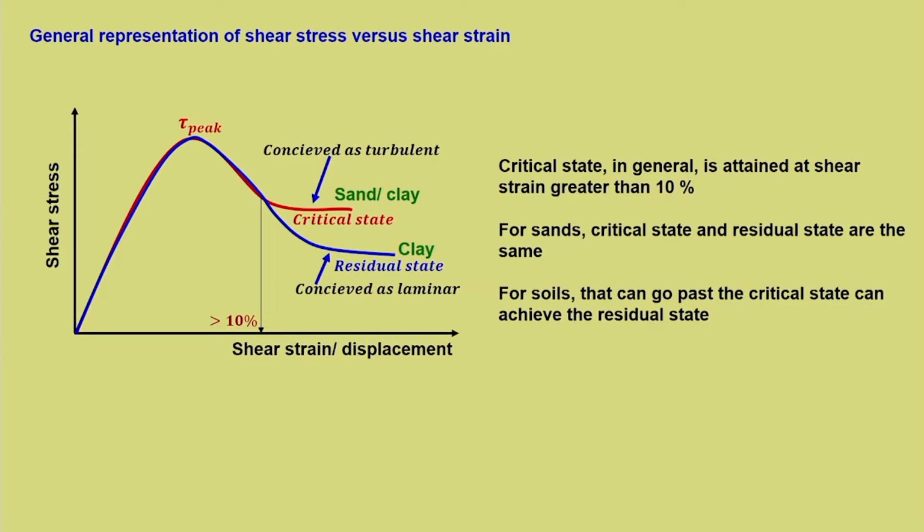Now let us go into the first step of understanding critical state, that is the relationship among shear stress, normal stress and void ratio. So, we are considering all the three elements which are needed for critical state. First let us understand in terms of tau and sigma dash. This is very well known to us, tau versus sigma dash and the failure criterion in terms of critical state friction angle, nothing to explain here. So, this is the critical state line. Earlier we called it the failure line, here now specifically we can call it CSL, critical state line.